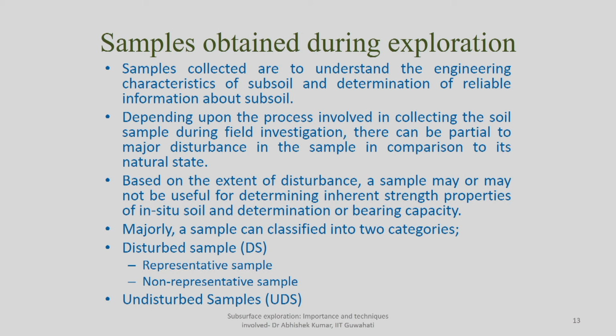Depending upon the process involved in collecting the soil sample during field investigation, there can be partial or major disturbance. In the case of trial pits, whatever disturbance you are doing is minimal, because within the chunk you might find some representative or minimally disturbed soil, which you can use for determination of engineering properties. But if you go for wash boring, the disturbance you are causing at the depth of the borehole is too much.